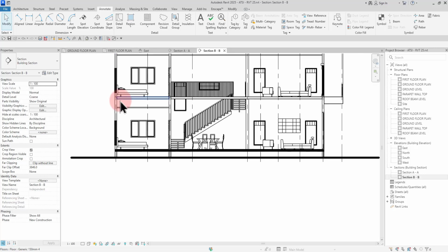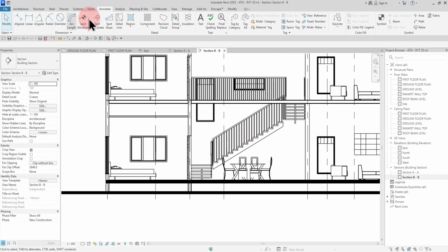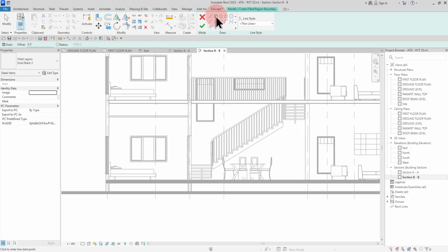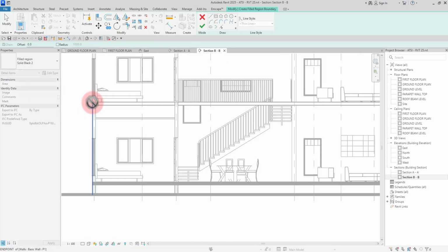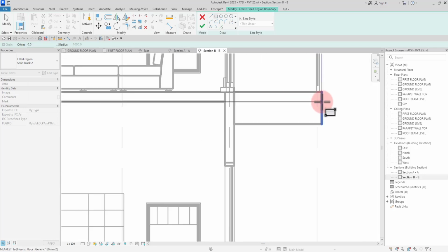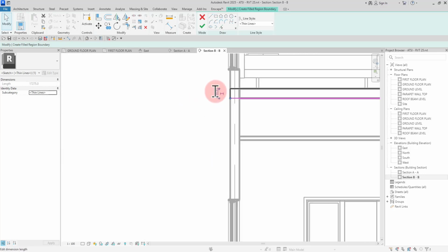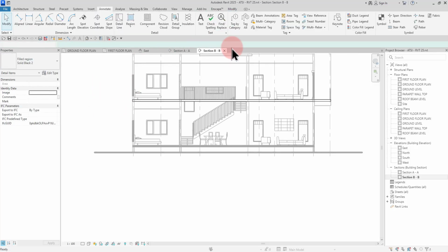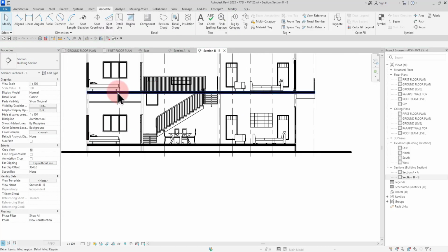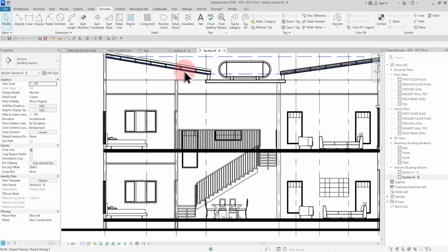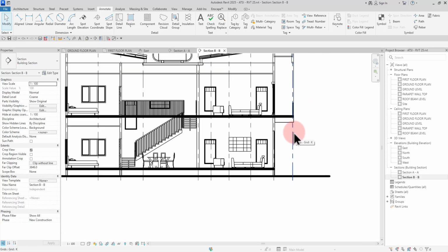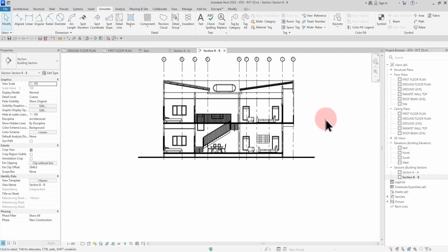We have to show the floor slab also for the first floor as well. So let's get back in there, solid black hatch, and we'll draw that in there as well. I want it to come all the way out to this piece right there. So click on that, and you can change this over here, input 150, so it's 150 precisely, and we finish that out of the way. So we've shown our floor slabs in there, and what we are supposed to show once again is our beams, our lintel beams, and all those other things, and all the columns in there, our structural elements.